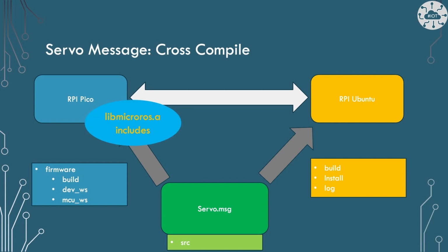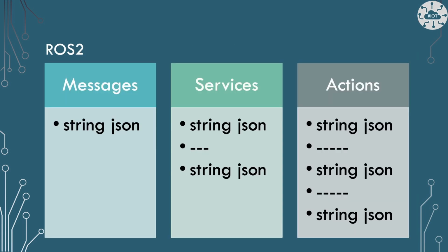To build the binding, we also need all of the supporting code for the Micro ROS library, so we actually end up rebuilding the Micro ROS library and placing our custom message within that library. This works and seems to be the recommended approach, but it's not ideal. It takes me the best part of an hour to rebuild the library. That truly slows down my iterative development. This has made me think a few times of standardizing on just three messages to encode everything as JSON. This would remove the type-safe nature of ROS and avoid some of the design principles, so this isn't the idea.